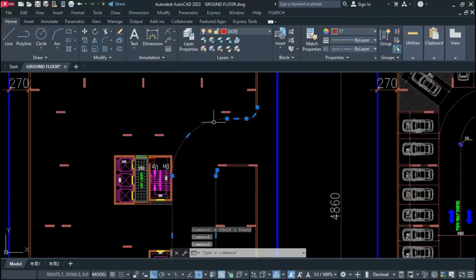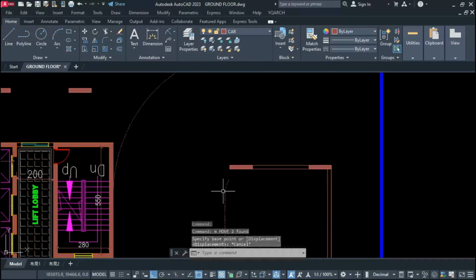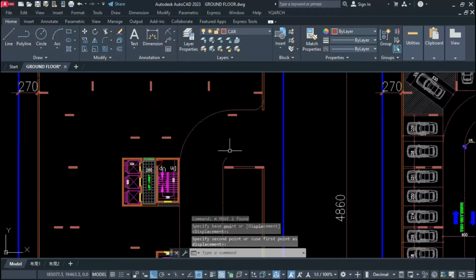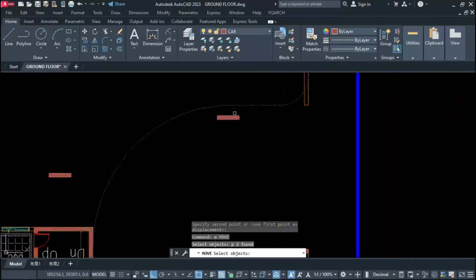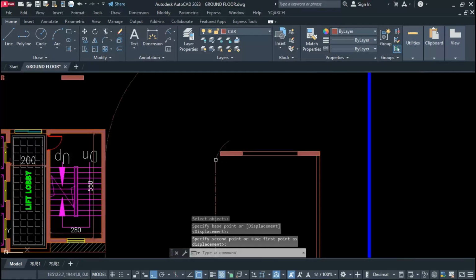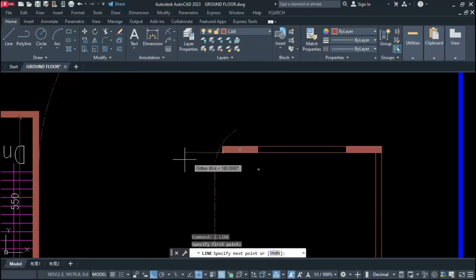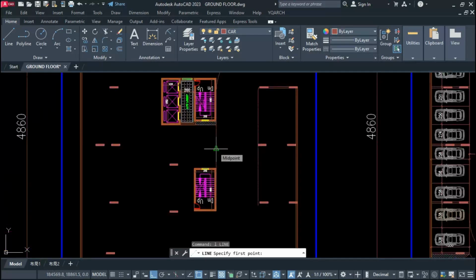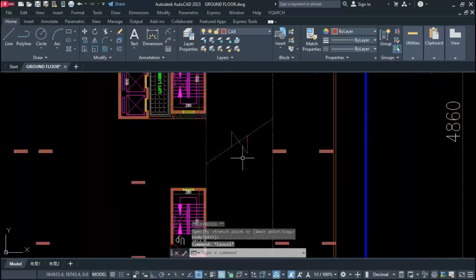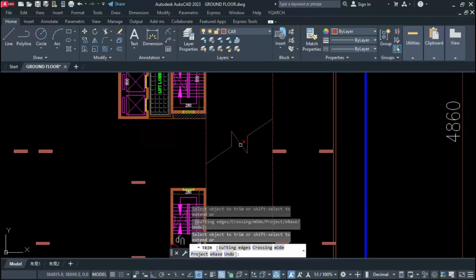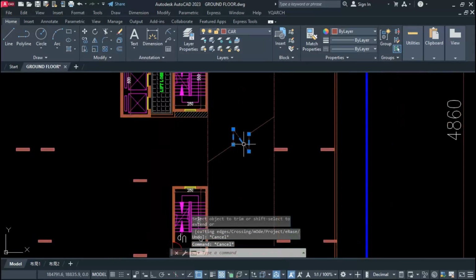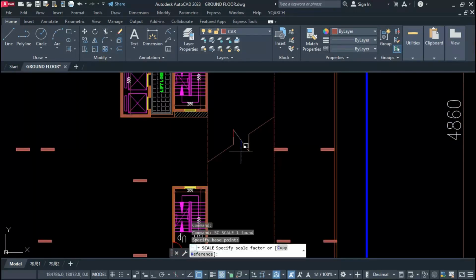Okay, so let this two part move because we have space over there. Let this move center to center, our column area. So this is the condition. We are getting our parking area, something like this. Okay, let this break line over here. Okay, so this is our 14% slab from ground to first parking, and rest will go 4%.